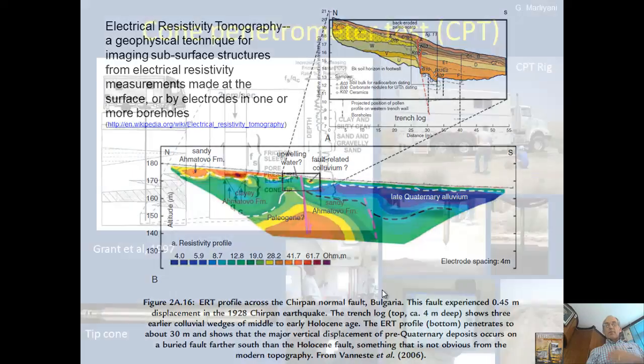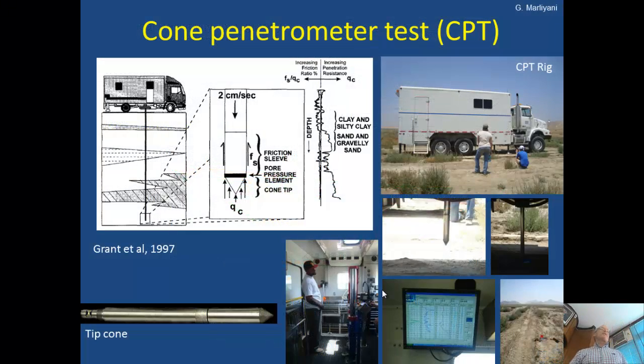Okay, so let's keep going. Another remote sensing method is to go down there and drill, doing different kinds of drilling, coring. Sometimes, though I don't show this here, there's large diameter boring. You can drill holes that are 1 meter in diameter, and people go down in and interpret. So this is done sometimes.